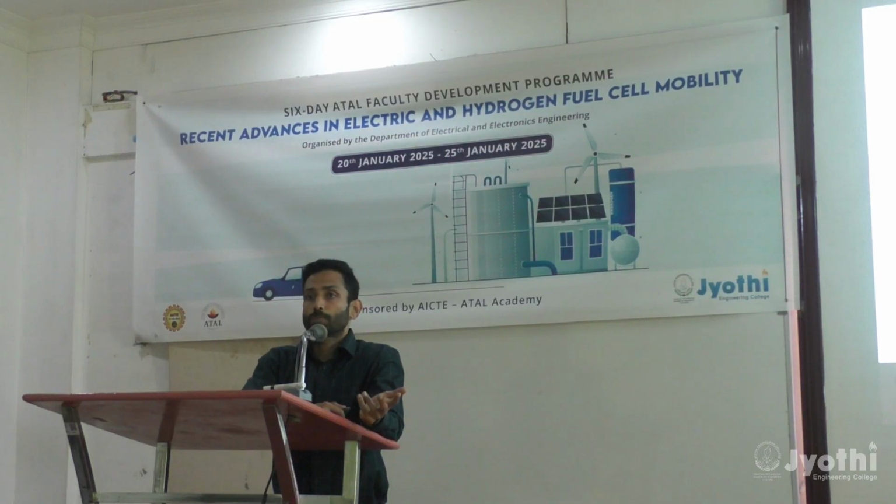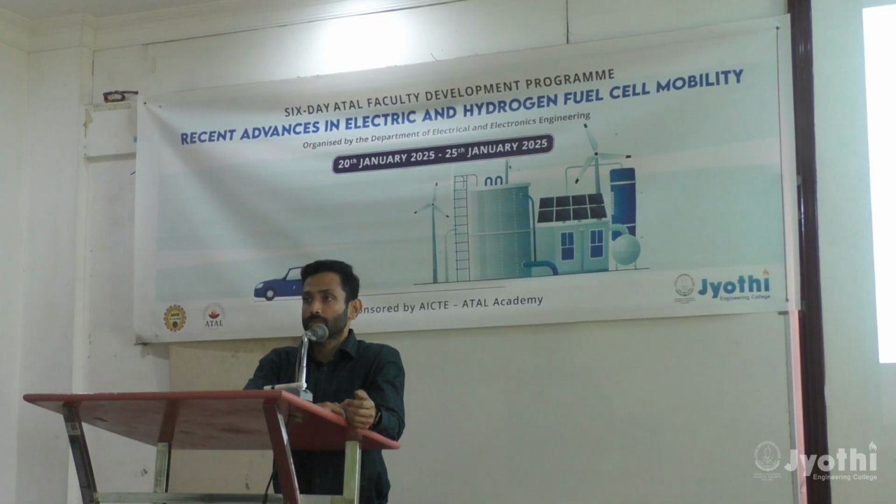Especially for mobility applications, which is again the focus of this FDP, if you want to store hydrogen and operate a vehicle, it could be a truck or even a small car, then you will need to store the hydrogen on board, and you do not have a lot of space on board. So you will store it in a cylinder. Let's say it is a 1 meter cube cylinder, and if you are only storing it at 1 kilogram per meter cube, then you can only store about 1 kilogram. In fact it is not 1 kilogram per meter cube, it is much less than that.